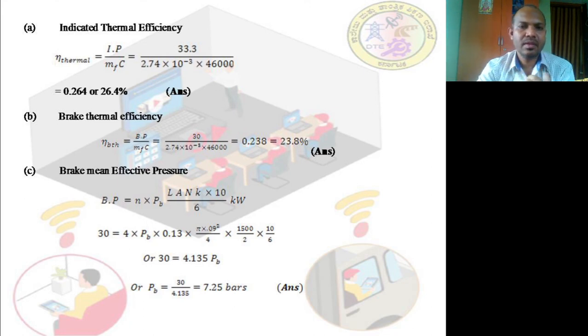And one more thing is that the swept volume or the volume of the cylinder should be taken. On certain occasions, instead of giving the area and stroke length, they will give the volume of the cylinder as so and so. The volume is nothing but area into length. Correct. Even if I want to find the swept volume, it is nothing but pi d square by 4 into L. So that itself is the volume of the cylinder. Since he has mentioned 4 cylinders, we have multiplied with 4. That's all.